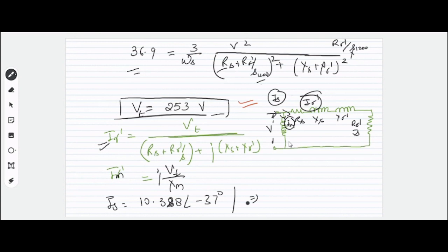And as your motor is delta connected, we can have this as phase current, and your line current will be equal to √3 times the phase current in case of delta connection. That's why the final answer will be 17.89 ampere. I guess now it's clear to the class how they have calculated this. Is this clear बच्चों? बताओ भाई. Yes sir, it's clear.